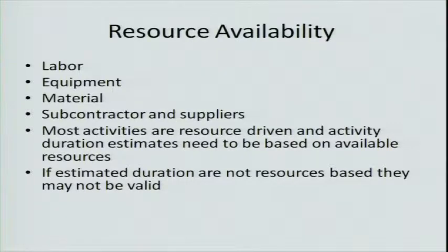Okay, if your durations are not resource-based, they're not going to be very accurate. If you think that, oh yeah, I know I can move 100, my excavator moves 100 yards an hour, so we're going to put 100 yards an hour into our program. But you don't take into consideration that your trucks can only move 50, and you're not going to get more trucks, then your estimation and your information is invalid. Garbage in is going to give you garbage out.